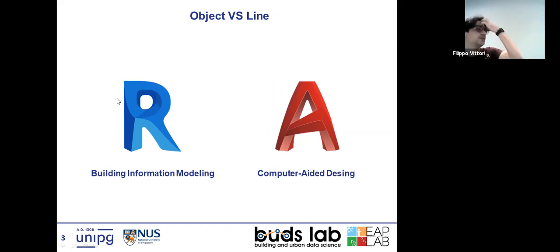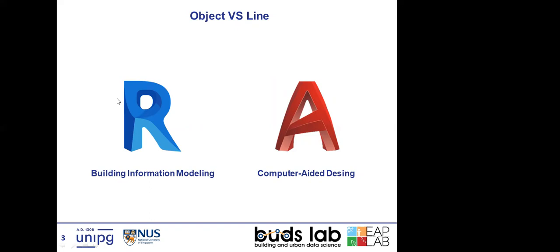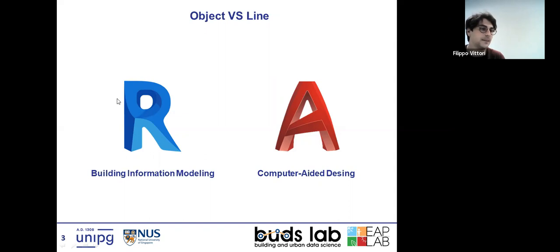Yes. Let's say the main difference is that they are designed with two different purposes. Revit is focused on and based on objects. AutoCAD is based on lines and drawing. So if you want to draw something, use AutoCAD. But you are right that if you start programming it and you look at lines like objects, then yes, you could say that you are doing something in the middle. But for instance, within a normal day in my job, I will use Revit to design a system, an HVAC system. Then if I have to schematize the system and make a single line scheme, I use AutoCAD. That's the main difference, even if I add attributes online, that could be layers, properties, blocks, a bunch of different properties, but probably it is still not the BIM paradigm.